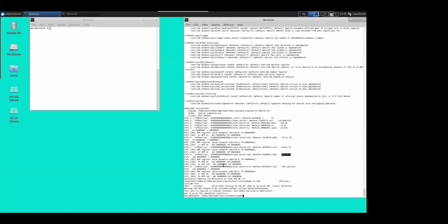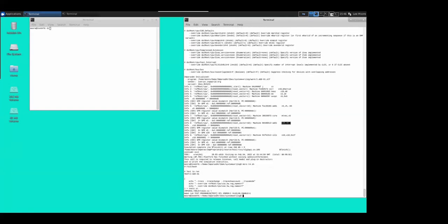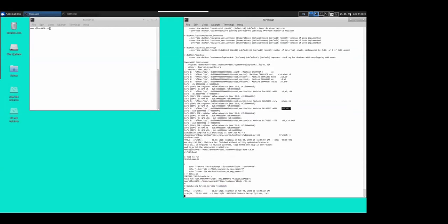Now let's turn on some further tracing. What I also want to do is turn on some tracing from the RVVI interface. Remember I said that there are clients that we attach onto the RVVI. One of them is controlling the Imperas DV API calls. And we have another one which we call the VLG to log, which is watching the transactions and can log those transactions out based upon what is occurring on that RVVI interface. So let's run that now. So now we're going to have some logging of the interface itself and of our reference model.